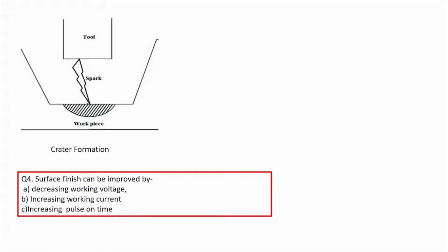Just a minute. So here the picture tells how the crater actually forms during the material removal process. How that removal of material takes place is explained based on one model. So here we have to remember some material removal equations. The material removal is 2 by 3 of pi r cube. Okay, so that r is the radius which forms due to a single pulse or spark.